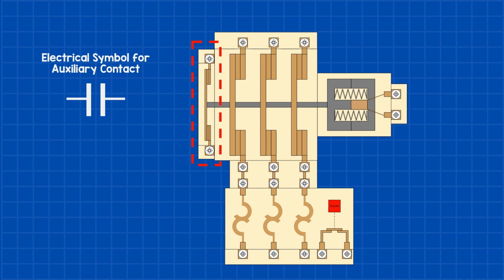Depending on the application, it may have one or several auxiliary contacts. Typically, one auxiliary contact is used to latch the control circuit, keeping the starter energized after the start button is released. We'll see exactly how that works as we go through this rung. Now let's go back and look at how the logic for this motor circuit works.